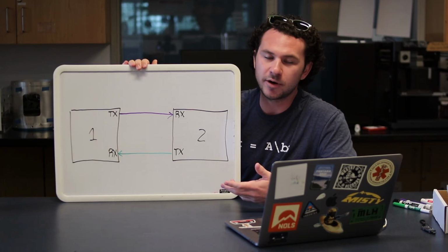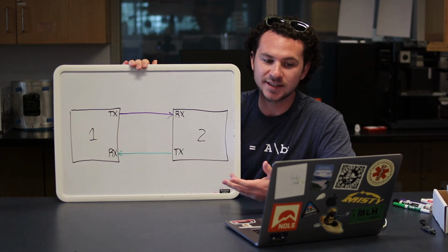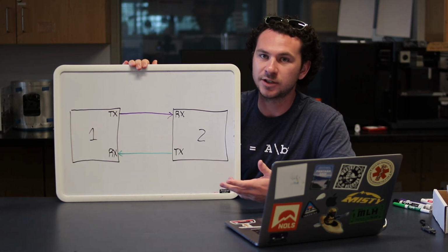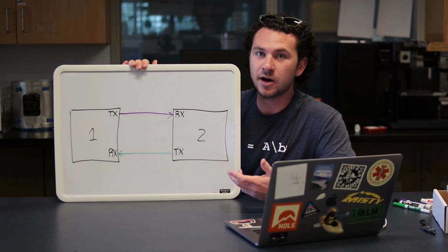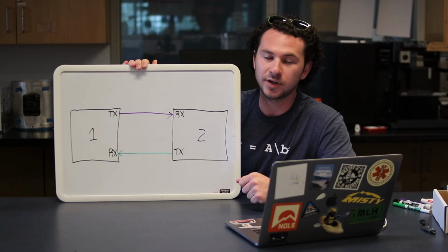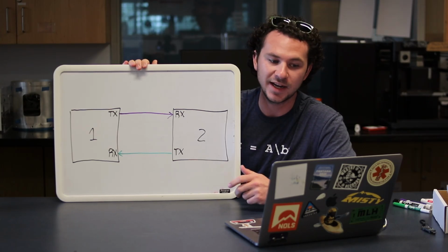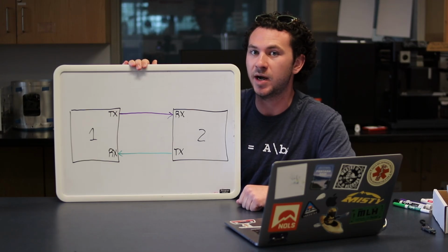It's still a useful protocol, and when we're using the serial class, you may recognize some of the commands as the same commands we use to interact with the Arduino serial monitor. This is because the Arduino IDE uses UART to upload compiled code to an Arduino device and receive data from the device to print to the serial monitor.